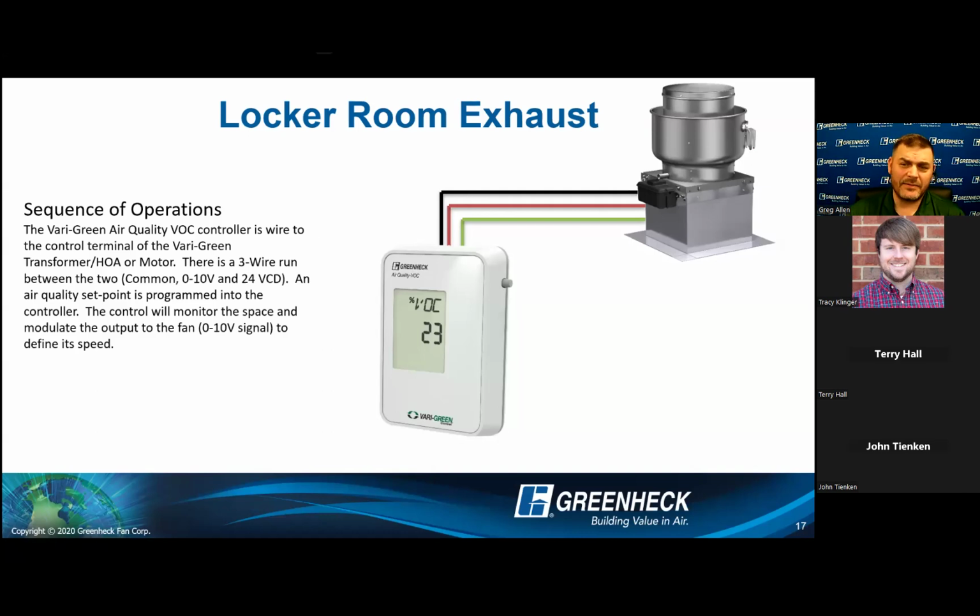Carbon monoxide is a VOC, so I see them in garages every once in a while. Now, the neat thing here is that VOC controller is not just a sensor, but it's a PID brain with its own sensor. So it's going to look at the environment, like this one, it can sense about 5,000 square feet of area.